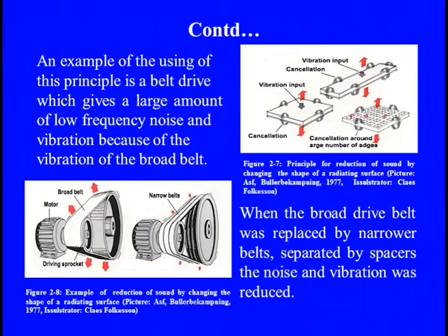Even on the top side, we have a clear reduction of the source by simply changing it. If we have a solid feature, there is a huge amount of transmission. But if we use the stepped perforated panels, the vibration and noise level can be straightway reduced. These are practical examples, and we know that if we can deviate the path of the sound or vibrating feature, we can absorb the energy or the molecular features associated with the transmission, and through that we can control the amplitude of the vibration.